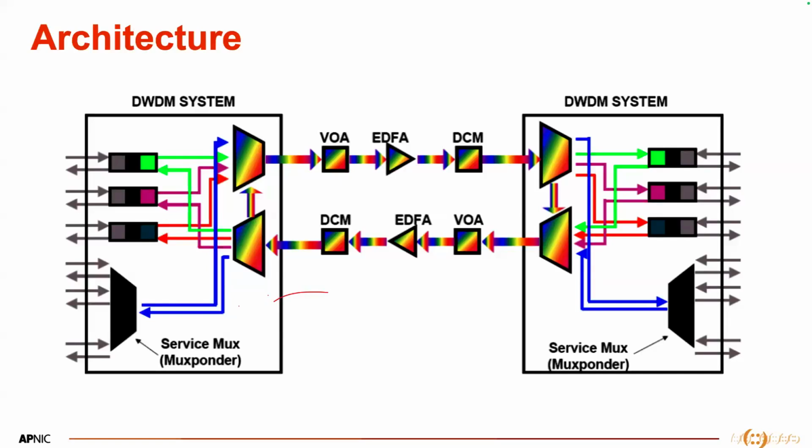At any station there will be a multiplexer and demultiplexer, and the signals go into the line cards, which convert the wavelength from color lambda to gray lambda, so the payload can be delivered to the client in gray lambda, in the 1310 or 1550 nanometer range.